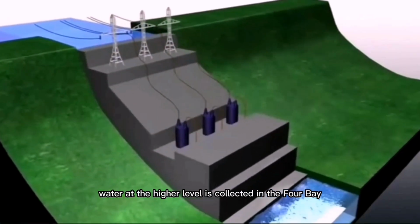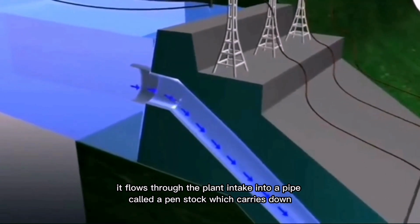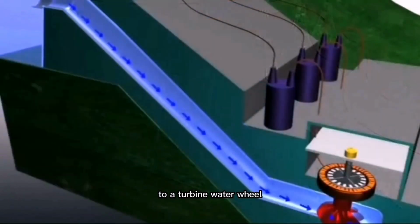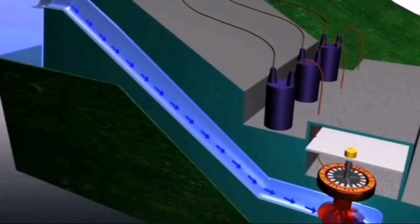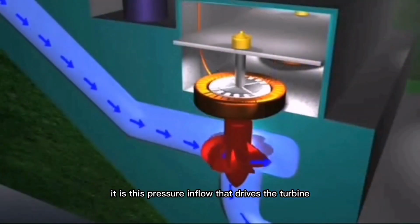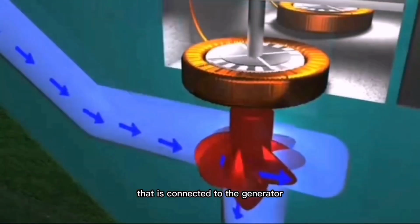Water at the higher level is collected in the forebay. It flows through the plant intake into a pipe called a penstock, which carries water down to a turbine water wheel at the lower water level. The water pressure increases as it flows down the penstock. It is this pressure and flow that drives the turbine that is connected to the generator.